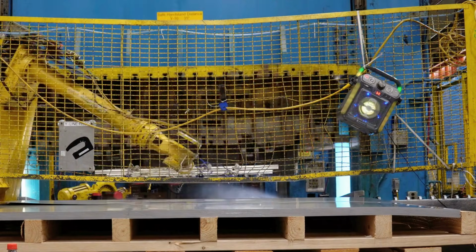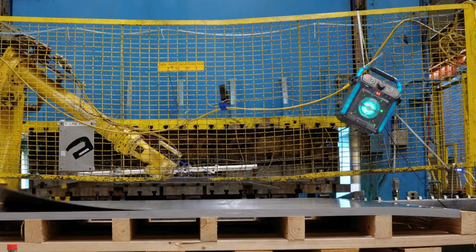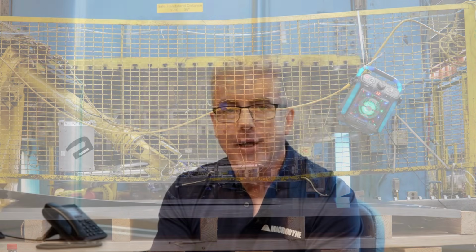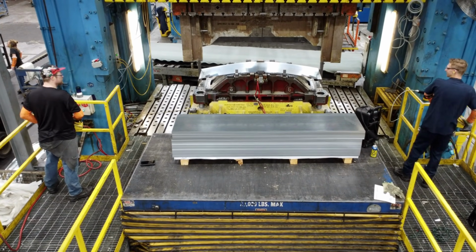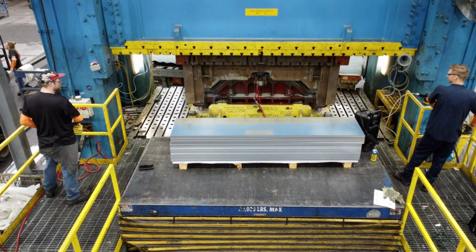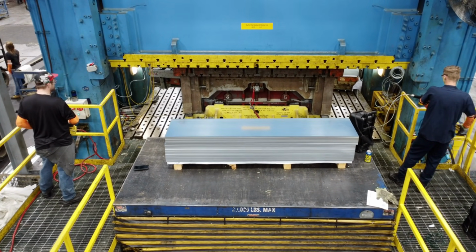That automatic correction becomes especially valuable when operating conditions aren't perfectly consistent. Closed-loop process is really used when you have a system that is not consistent all the time. So if you have product that goes into the press at different temperatures, or maybe you've added some lubrication to it that creates a slightly different motion every time, the closed-loop motion control will compensate for that.